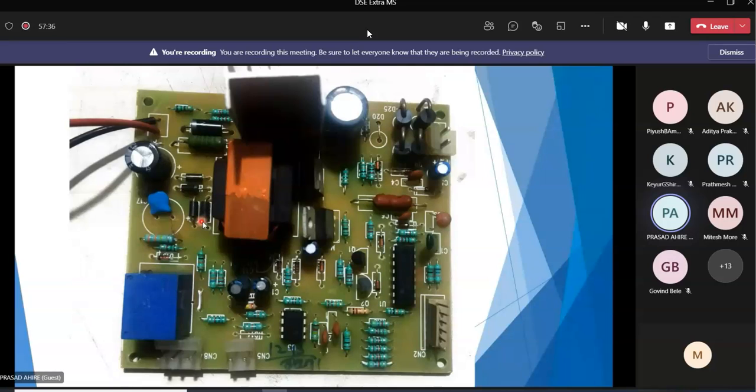The diodes rectify the supply into pulsating DC, which is given to the filter. The capacitor filters the supply into DC, and the DC is given to the battery and charges it. When the supply is out, the supply is taken from the battery and given to the circuit, and with the help of the step up transformer, the supply is given to our appliances.